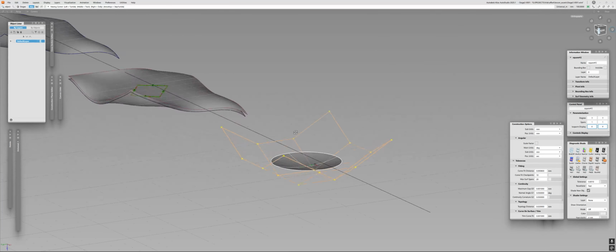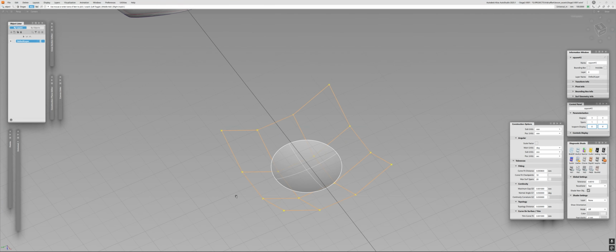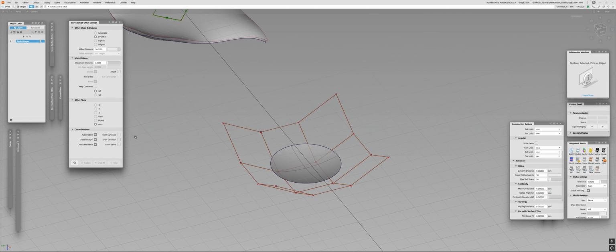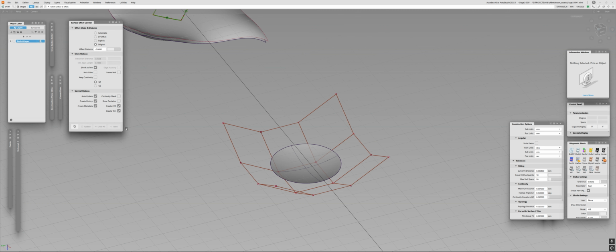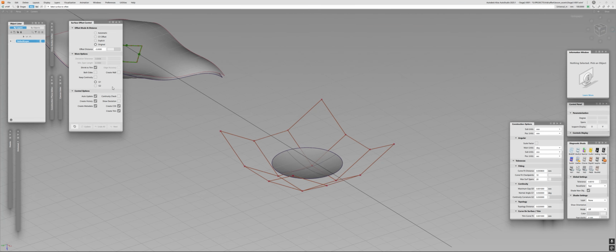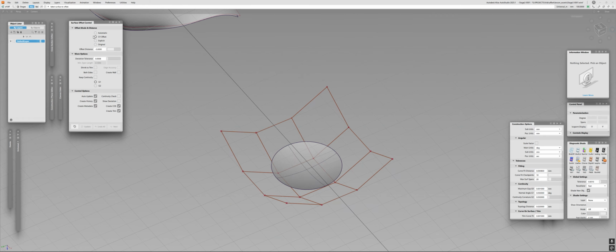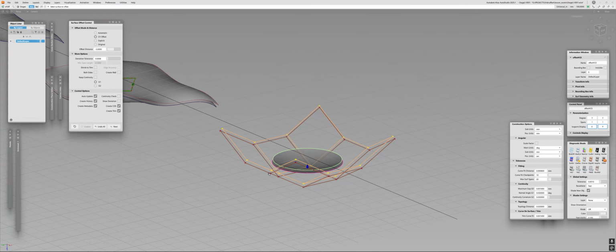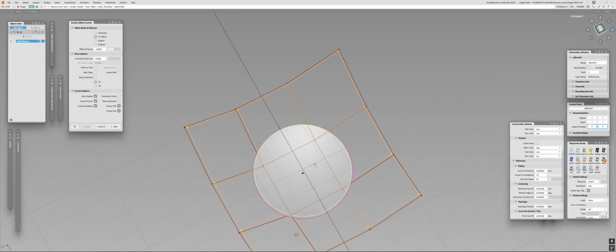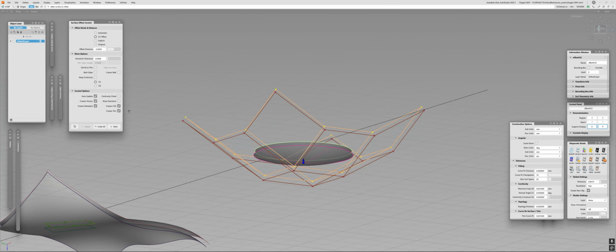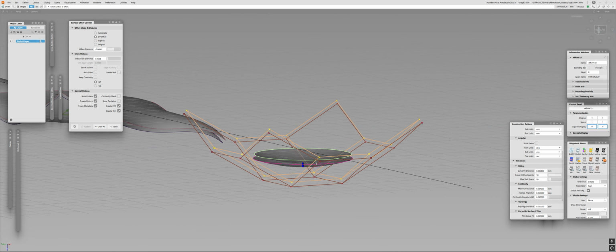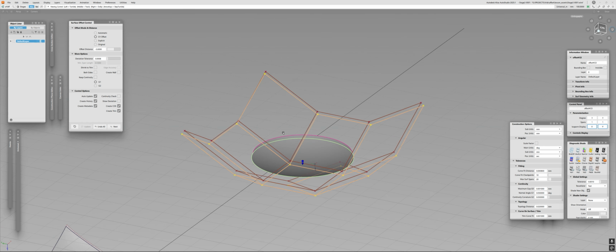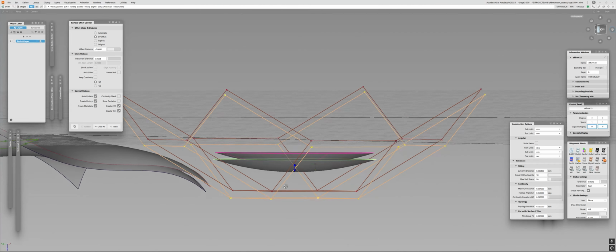So this one, as you're going to see, was a surface, and it was cut in the form of a circular shape. It has a circular cut. Now, this is just an example for a specific option, which I didn't really specify. It's called shrink to trim. Right here, it's activated, so let me just deactivate it. I'll go to the CV offset, click on the surface and activate its domain of control vertices. As you're going to see, I have the CV offset method activated. I move to the geometry. Once again, I don't remember if this is the outer shell, it always goes outwards, inwards.